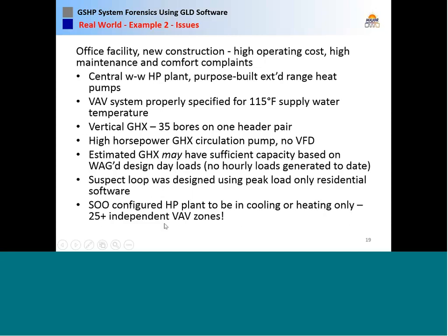And the other issue we identified off the bat was that the sequence of operation had the entire heat pump plant either in cooling or heating only, with over 25 independent zones in the facility. So either the entire building was cooling or the entire building was heating. So very few people were happy unless they controlled the thermostat.